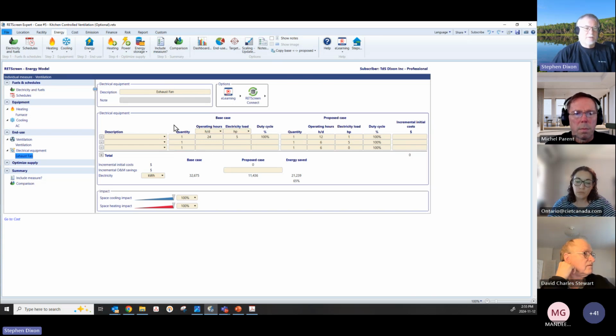And then likewise, we have to have 3 regimes or 3 different modes for the electricity running the exhaust fan motor. In very simple terms, I didn't account for the efficiency as Michelle did. I simply had 5 horsepower here. The 5 horsepower is at full flow, that's the 6 hours, and I approximate 1 horsepower with the drive for the half flow situation for 12 hours.